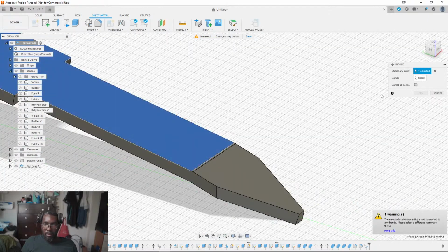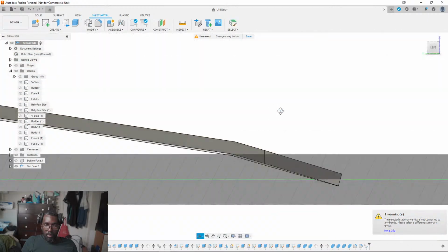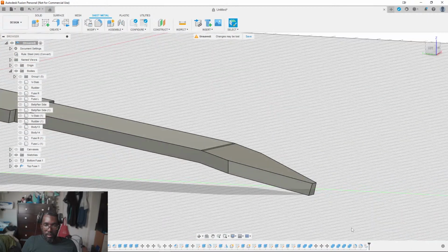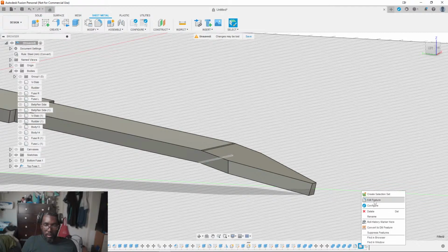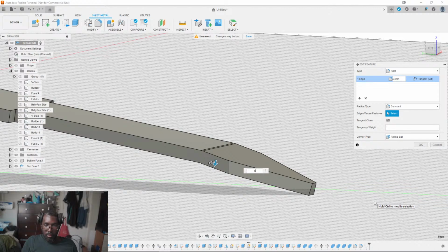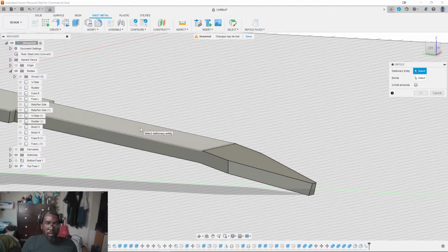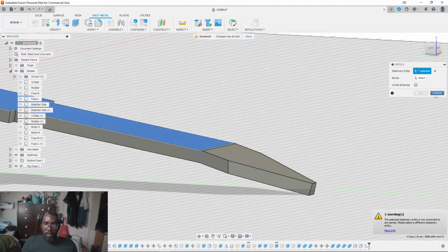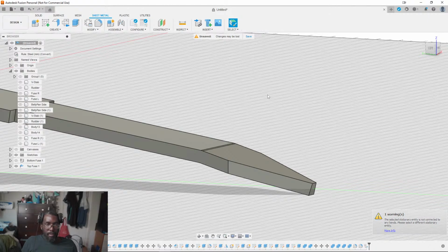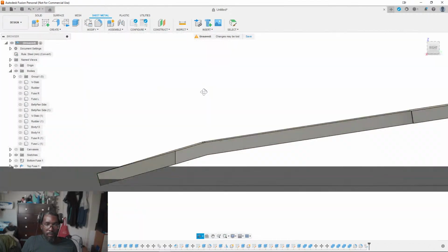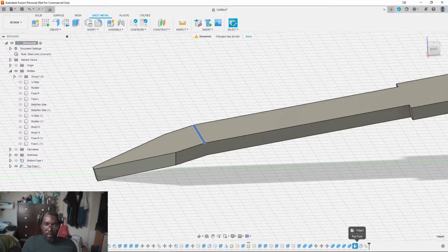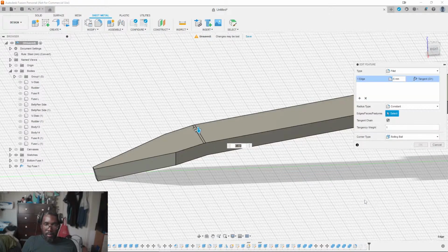Alright, let's try now. Unfold. At least the front. Nope, nothing has been detected. So edit, let's also make this 6. And then unfold. Damn, no bends were detected. Alright, so edit. Let's make this 10.